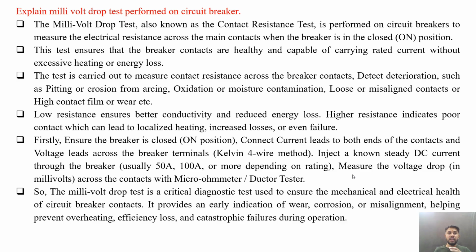Explain millivolt drop test performed on circuit breaker. So, the millivolt drop test, also known as the contact resistance test, is performed on a circuit breaker to measure the electrical resistance across the main contacts when the breaker is in the closed, that is on position. This test ensures that the breaker contacts are healthy and capable of carrying the rated current without excessive heating or